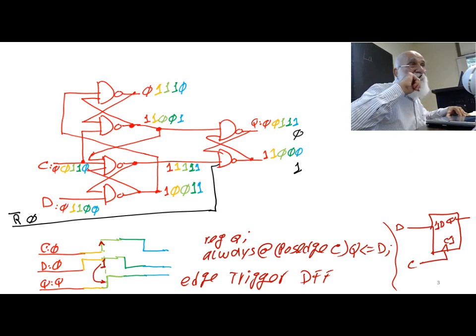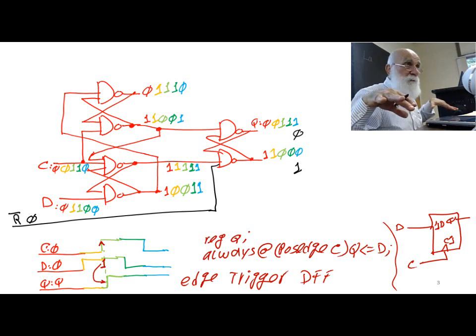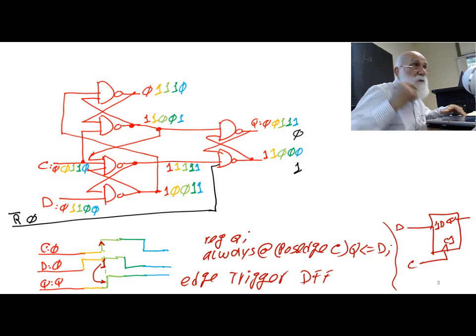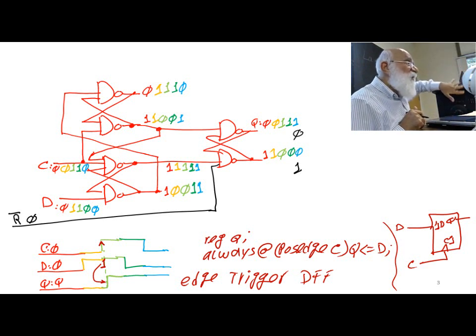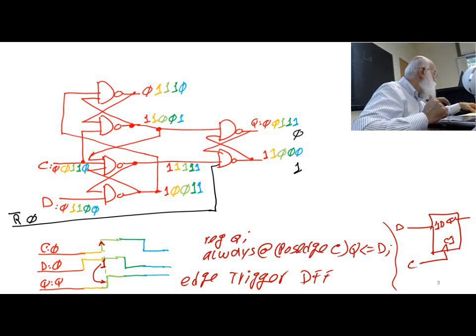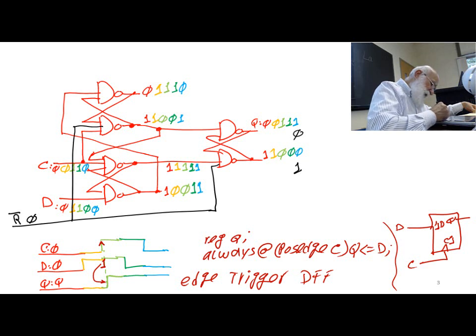Okay? If I want to make it permanent so that when it becomes 0, or when it becomes active, the output resets, and when it goes back to 1, which is normal mode, the output remains at that reset value, this is what I interpret as reset. If I want to do that, I have to also affect the stages before that. That's why I'm going to take this input, not only to that output, I'm also putting it into this and into this.